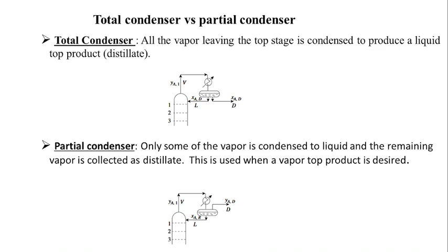The 4-inch bubble caps will typically have around, say, 65, 70 millimeters of height. All the slots have to be submerged. Not only the slots, above the cap head also, there should be a level of liquid. So naturally, your weir must be of a certain height, which will ensure this.